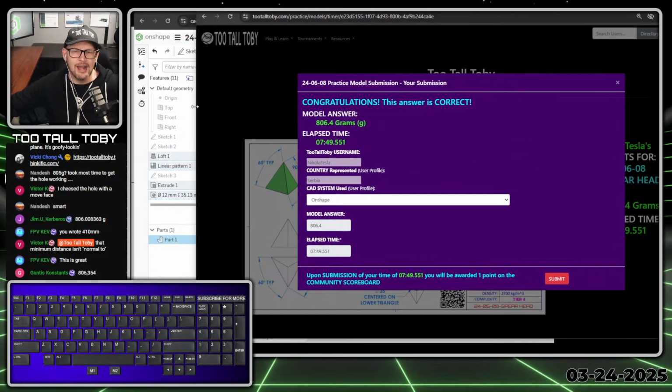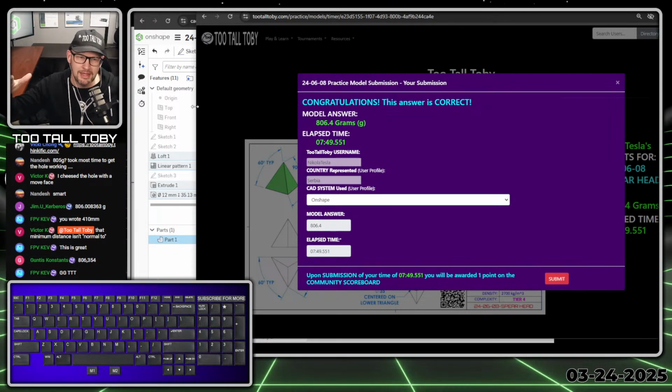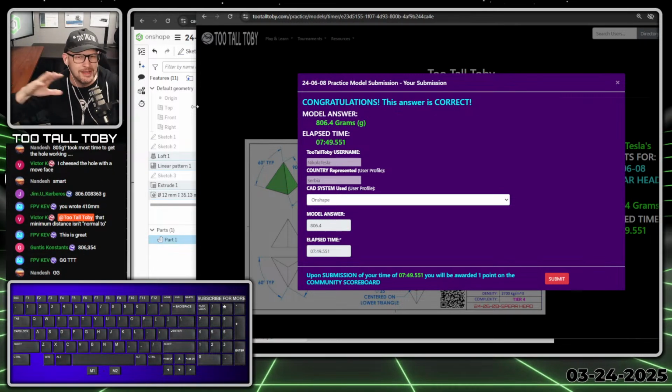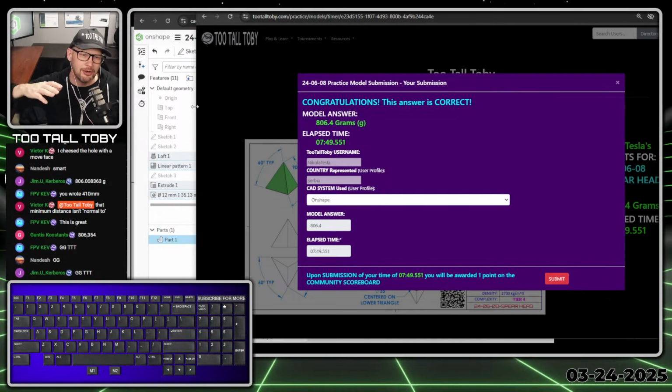So, like I said, I don't know if I would necessarily recommend that kind of hack and slash at the end. It depends on what the working environment is. If you're just trying to get something out for 3D printing and you're still early in the prototype phasing, I think that's fine. If you're doing something that's going to be manufactured and you're going to get 1,000 of them made, then I would go through and do it the right way with a cut revolve, or I would really make sure that number is dialed in before I proceed.